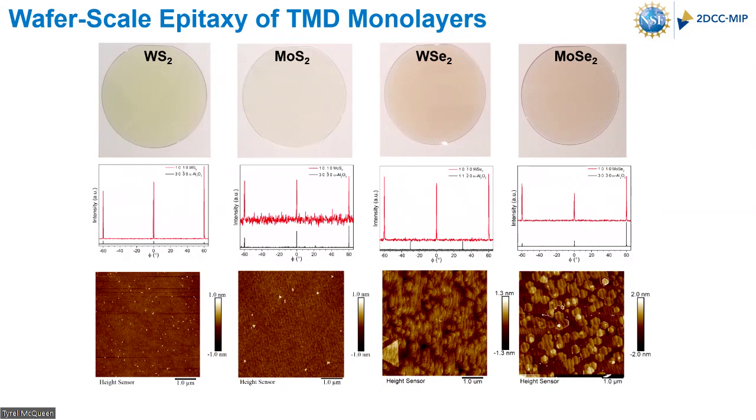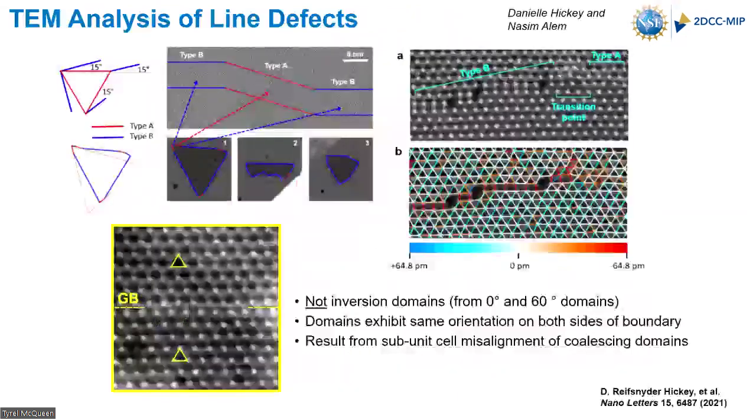Yeah, that's a really interesting point. We have not done extensive work on that, but when we grow these, we typically do anneal them post-growth, in the growth chamber. Mostly we do that because if we don't, we end up with some little tungsten or molybdenum particles on the surface. So we anneal them just to give those particles a chance to move around. But we're also very interested to study whether there's some motion of grain boundaries in these films as a result of annealing. We haven't really looked at that yet, but I think that's an interesting area as well.